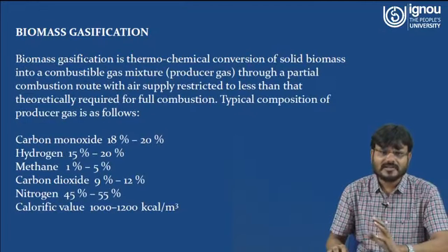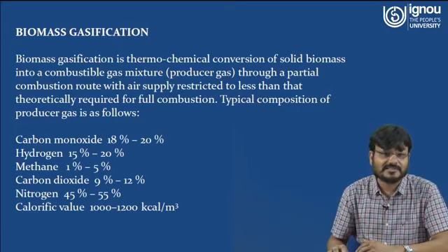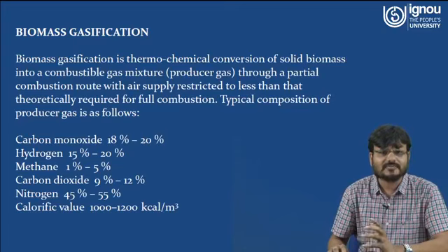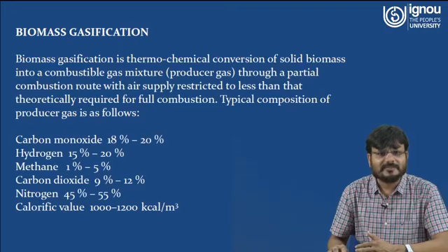Now, the interesting question is: what is biomass gasification? Biomass gasification is basically the thermochemical conversion of solid biomass into a combustible gas mixture, which is also called producer gas, through a partial combustion route with the air supply restricted to less than that theoretically required for full combustion.